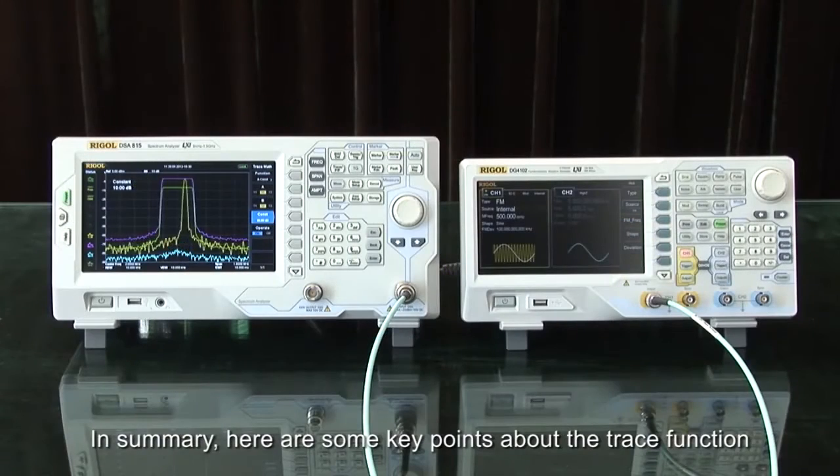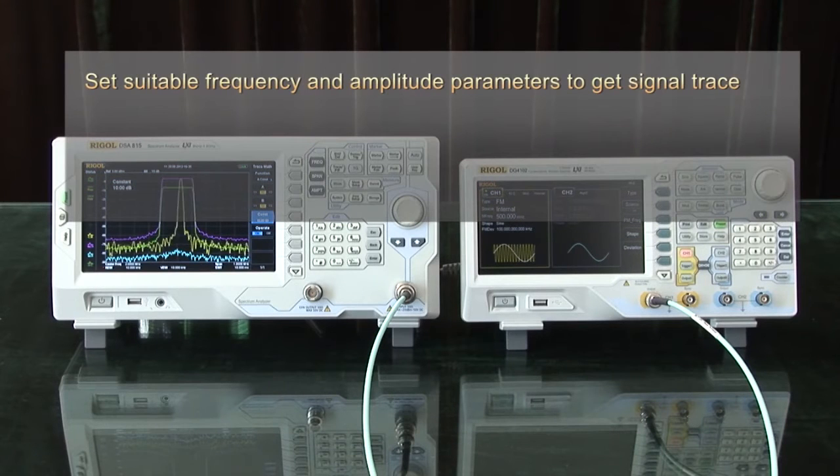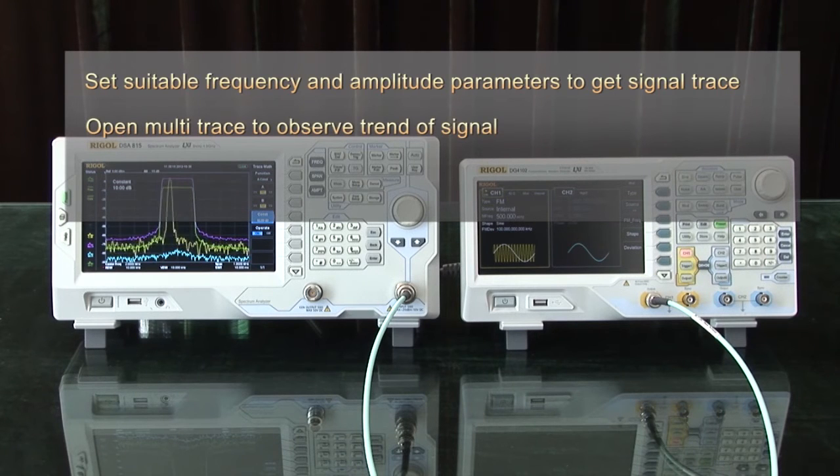In summary, here are some key points about the trace function. Set the suitable frequency and amplitude parameters to get the signal trace. Open multi-trace to observe trends of signals. Choose suitable trace types depending on the different memory.